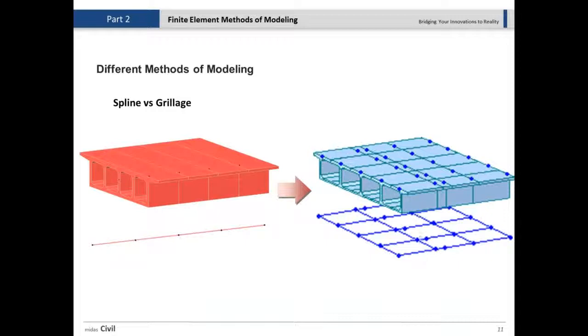And another action is it gives the additional torsional behavior, torsional stiffness. So if you can imagine that if you want to bend this one in the x direction, so out of plane, it can easily rotate, right? If it's just one of these girders right here. But if you keep them all together, definitely we have a larger torsional bending stiffness in the out of plane directions. So that will be guaranteed as well.